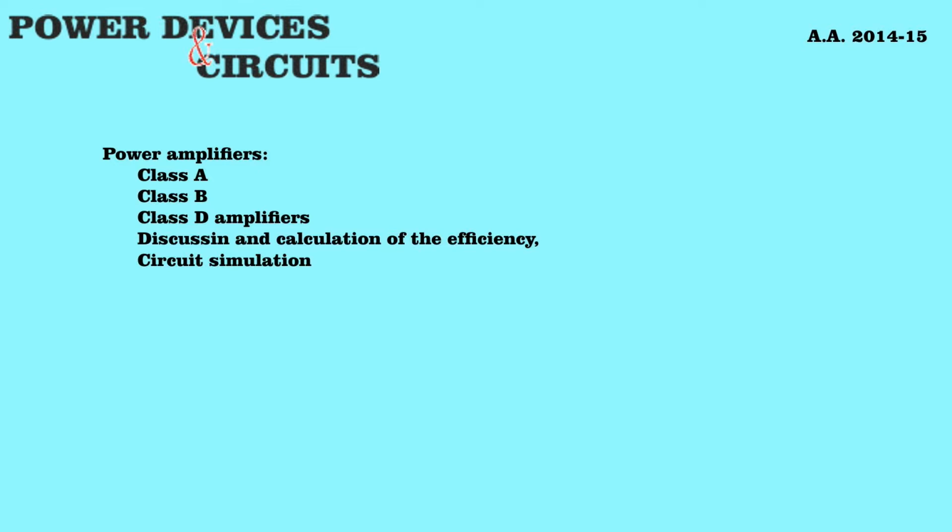So these two power supplies will just dissipate the same amount of power in one period, and the power dissipation is twice VCC multiplied I0, which is the power provided to the load. The load will have a sinusoidal output with a peak value Vp, and the peak current will be Ip. Just integrate the multiplication of volt and current to get the load power, that will be Vp Ip divided by 2.